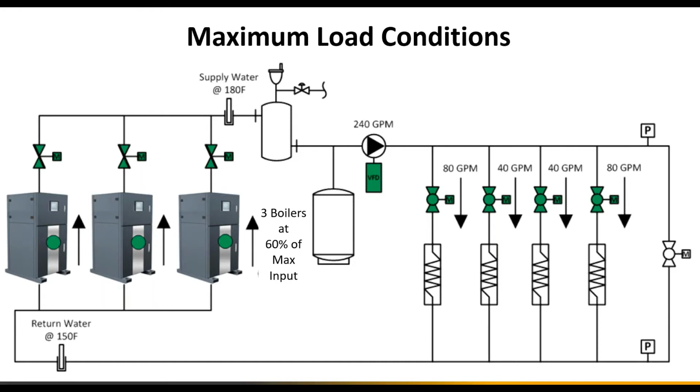You may have a duplex pump for redundancy, but especially with fire tube design boilers, which have a greater degree of flexibility in terms of flow rate through the boilers, we can install high efficiency systems with very simple piping, really limiting the electrical consumption as much as possible, and have a highly efficient system, in this case running a 30 degree delta T on design day and achieving condensing operation through the bulk of the heating season.